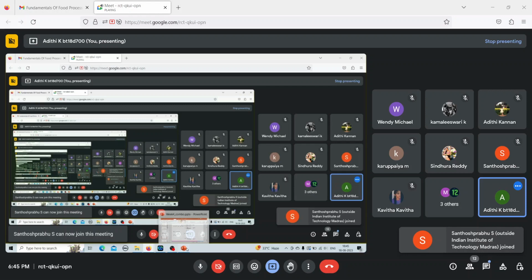So in a backward feed evaporator, steam enters one of the effects. It need not be the first effect, it need not be the third effect. It can be the other way around also. You can enter the feed in the first effect and the steam in the last effect. Anything is fine, but basically your feed and steam will enter in different effects. So statement C is false.